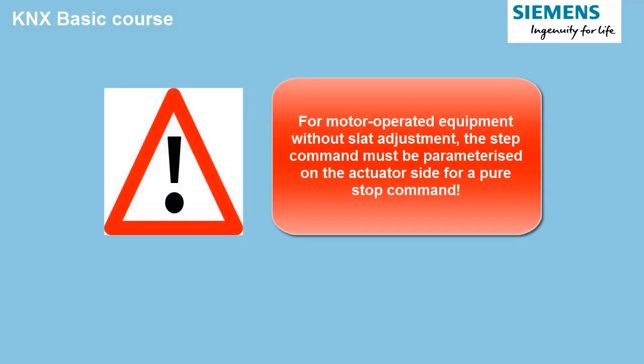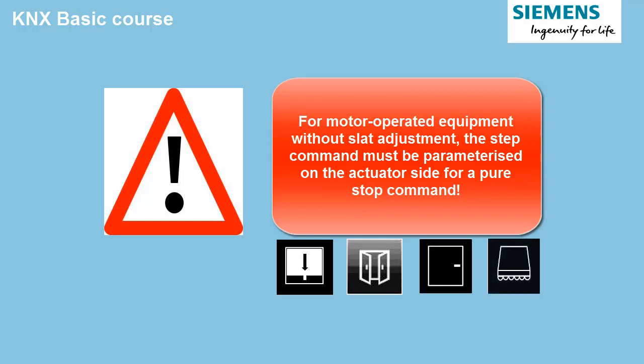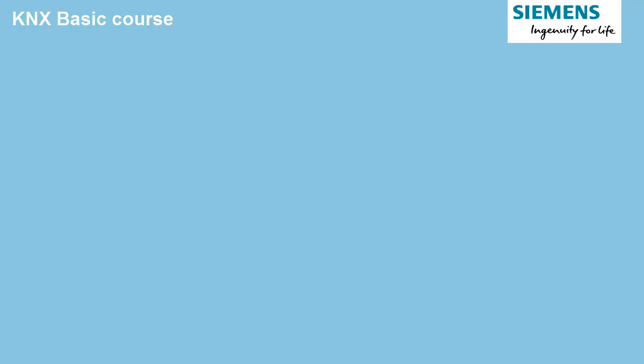Useful hint for the control of other motorized equipment, such as windows, awnings or roller blinds. You must set the type in the actuator correctly. Default is always Venetian blinds. If you don't change it for roller blinds, then each time you press the button short, they will also move for a short time, which however often annoys the user. Only if the parameter is set to type of shading roller blinds, there won't be movement when sending step-stop telegrams.